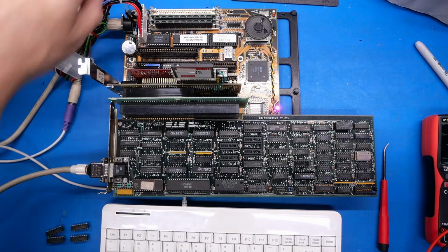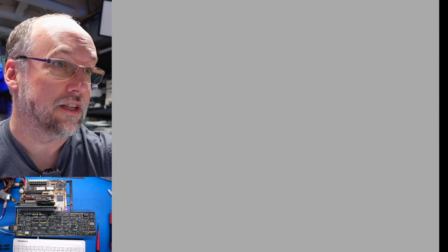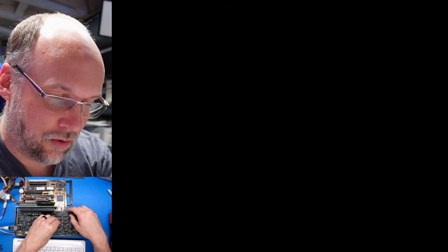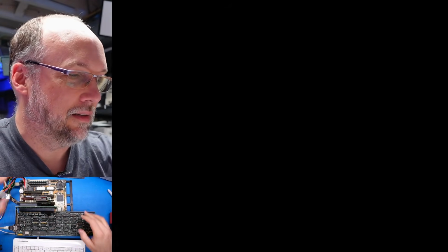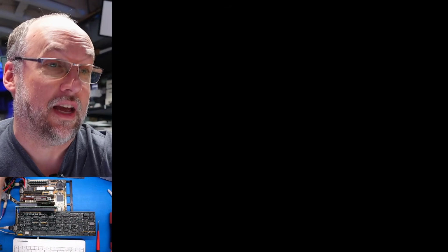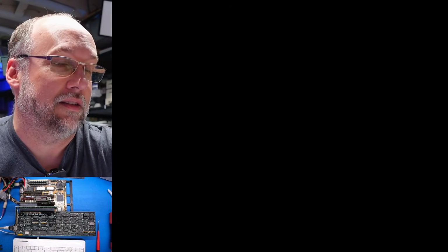It's still beeping. It could be that the RAM layout is not what I expect, and it's not just linear, but maybe it's interleaved inside the memory in some special way. What I'm going to do is install all 4 of the chips on one side, and let's see if we start to get some amount of text. It's going to be all messed up because we're going to be missing 4 bits. We're only getting 4 bits of the memory.